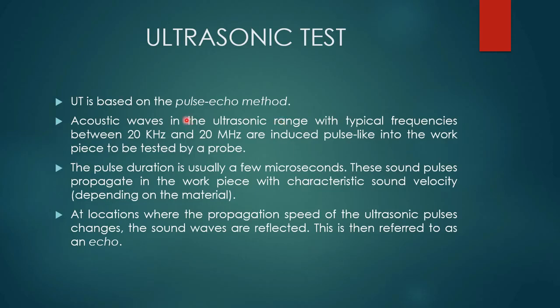So ultrasonic waves are waves with frequencies from 20 kilohertz to 20 megahertz, which are induced pulse-like into the workpiece to be tested by a probe. The pulse duration is usually a few microseconds. These sound pulses propagate in the workpiece. These sound pulses will go into the workpiece with characteristic sound velocity.